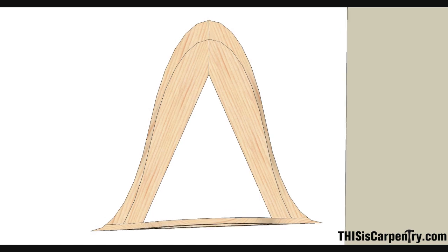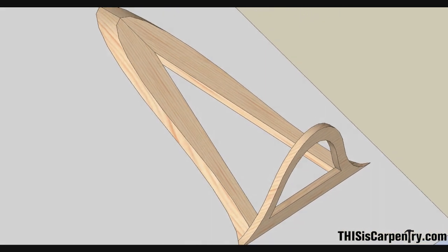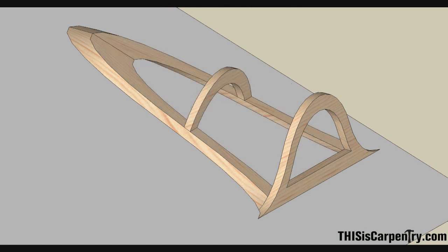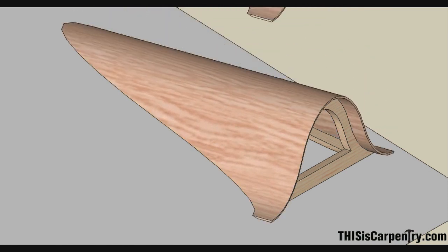This method of using 2D drawings to project points is continued in order to develop the inner valley and the shape of the additional rafters. Once framing is completed, sheathing is applied and the dormer is installed.